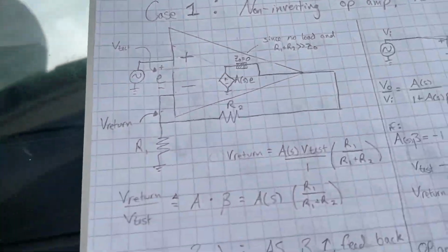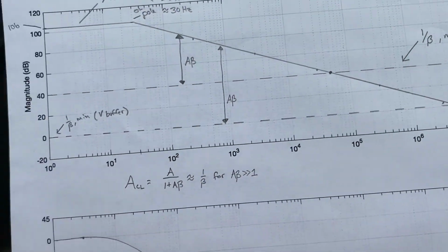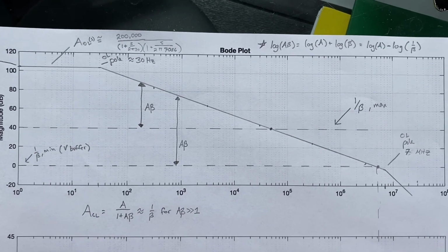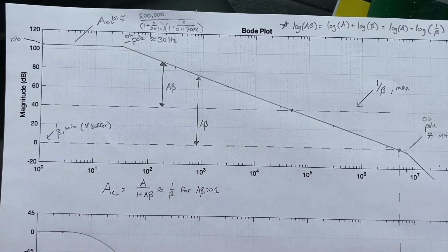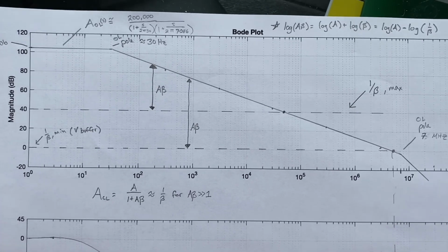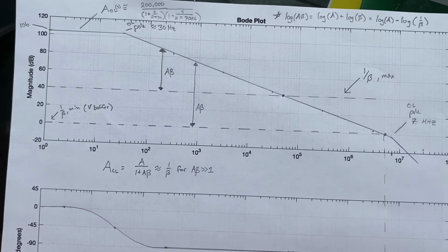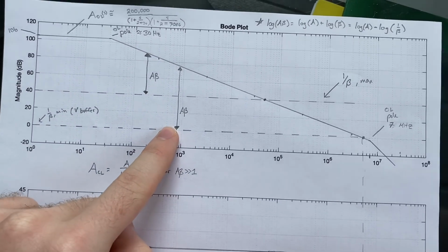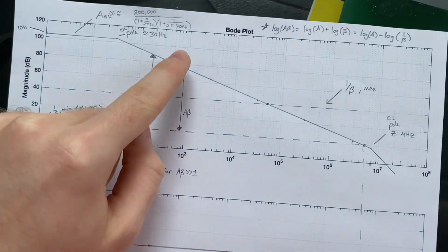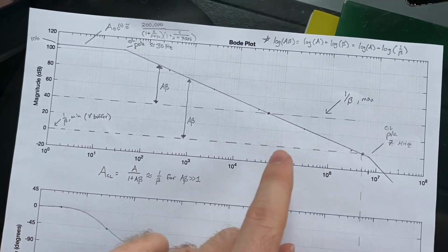And here we have it on some graph paper as well. The loop gain is really the difference between the curves of A and 1/beta by log rules, in the top right. For unity gain, 1/beta is just 1, and our loop gain is really big for a large bandwidth of frequencies.